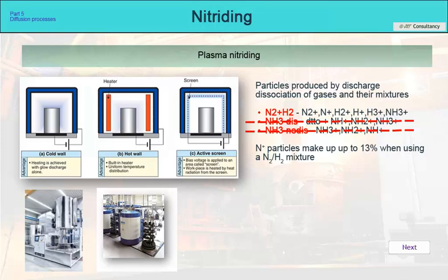They can have a DC cathode voltage source rectified from the mains voltage with a frequency of 50 Hz, but they can also be high frequency with a variable pulse, usually up to 1 kHz. A special case is the devices with the so-called active wall, where the actual discharge that splits nitrogen is in the form of a circumferential network in a vacuum vessel.